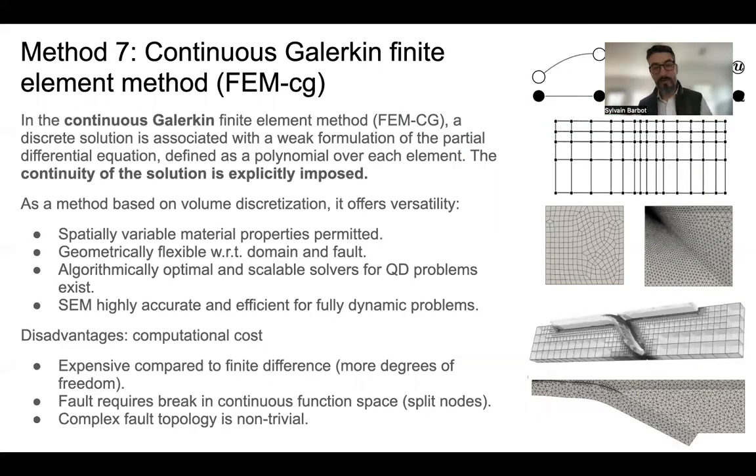So other methods based on volume discretization are finite element methods. So the so-called continuous Galerkin finite element method is based on a weak formulation of the partial differential equation, where the solution is represented as a polynomial for each of the elements of the mesh.